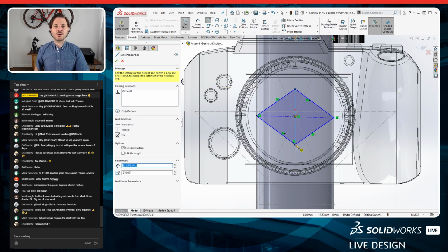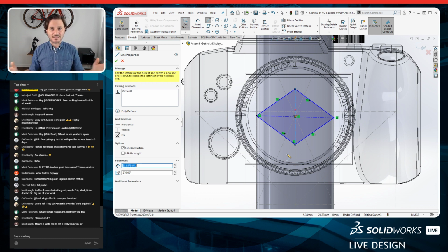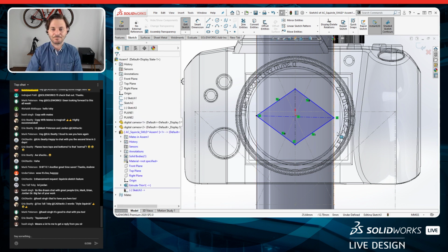And as Jordan showed you a couple weeks ago, you guys know that if you want to sketch lines and you don't want to have a tail on it, if you click, hold, and drag a line, when you pick your finger up off the click, when you unclick, what word am I looking for here? If you unclick, when you lift up your finger, it ends that sketch segment. So I don't have any tails. I don't hit the escape key or anything like that.